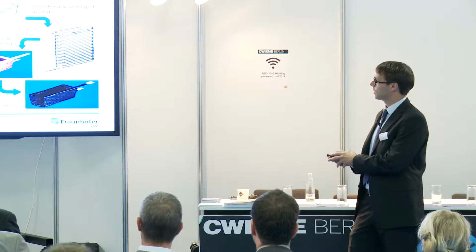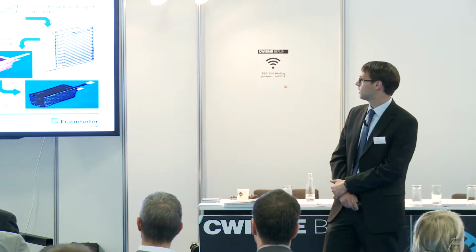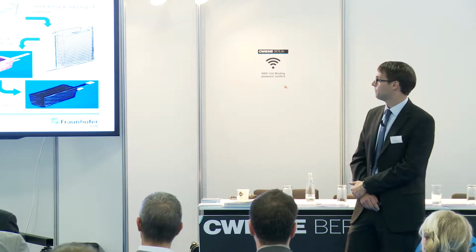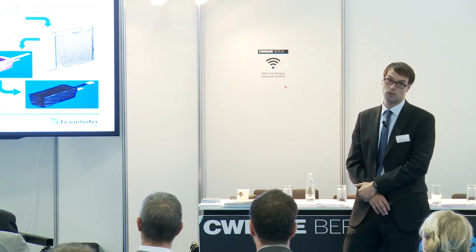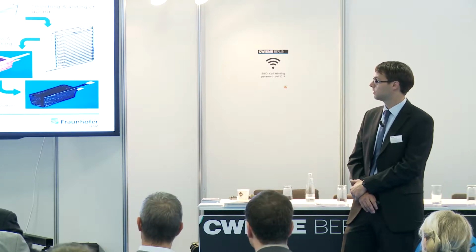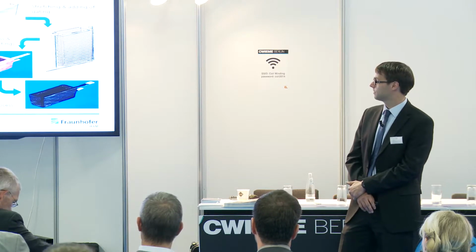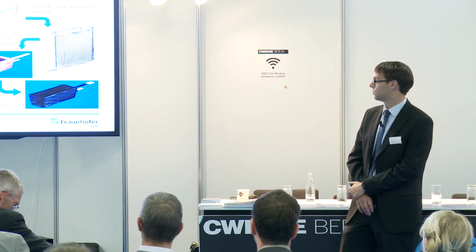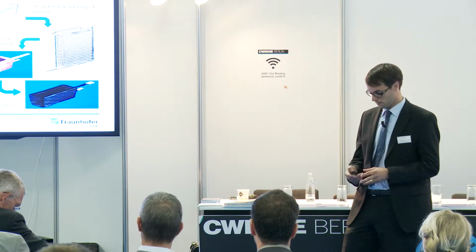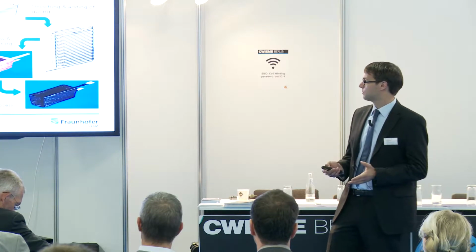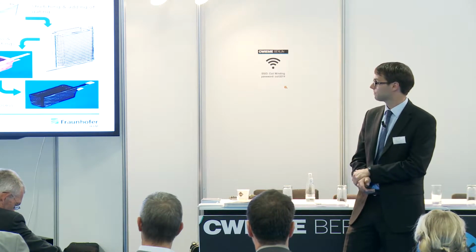We take the coil, we construct it with a flat conductor arrangement, shown on the upper side of the picture. After that, we do a stretching of the coil geometry, add the gatings, and use a casting process. We can use different casting processes. I will give an overview later of the used casting processes. And after the casting, we remove the gatings, do the insulation process, and have a coil that is ready to be stacked on the lamination to mount the machine. And this casting process offers some advantages in terms of the electric behavior of the machine.